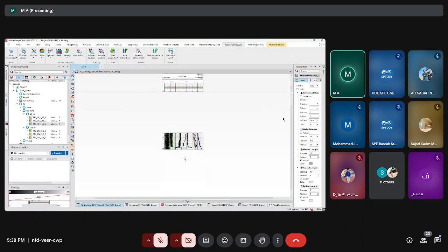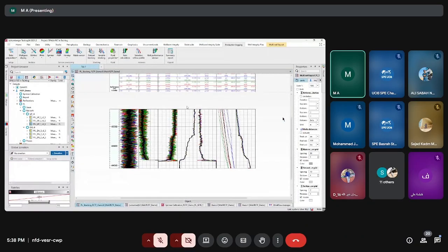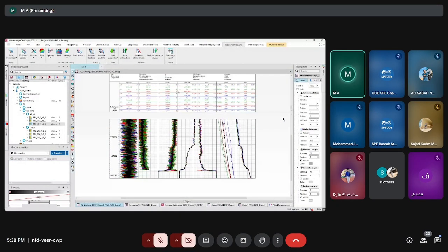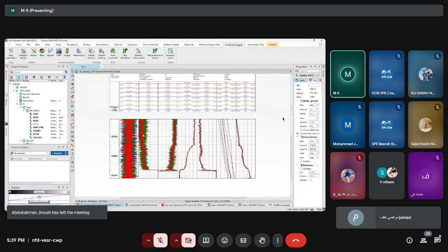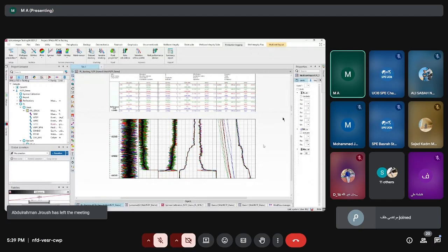And this is how the data stacking will look. You see here the black curve. This is the average of all the passes, the average of all the caliper, and the average of all the water holdup, the average of all these 6 passes, okay? So when I'm done with this one, it will create a new data set called data stack that has only these black curves that I needed in order to do the rate calculation. Okay, so now I am done with the data stacking.